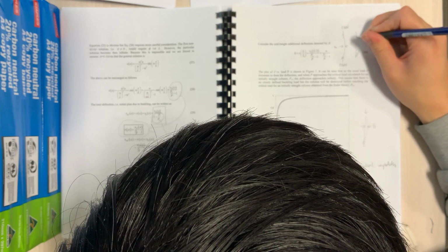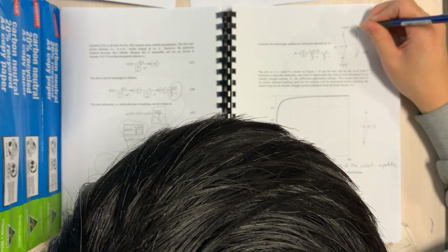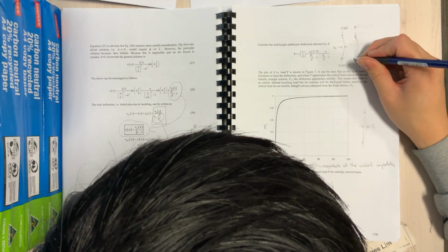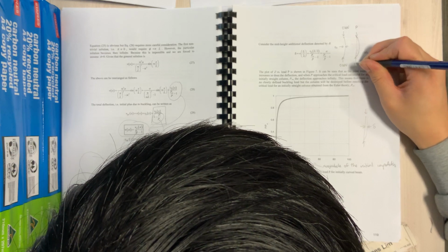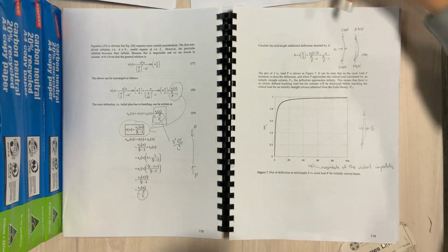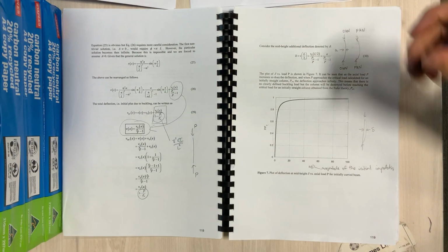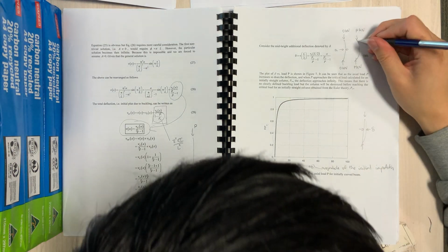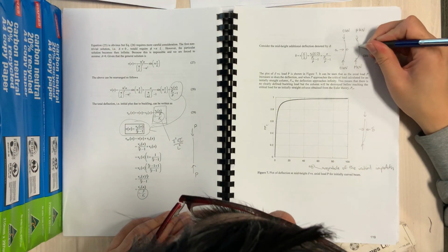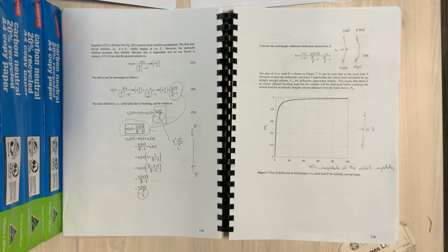And we're sticking a load on. So we're sticking an additional load on. That's P kilonewtons, and that would be P kilonewtons. So we're moving from the 0 kilonewton state. I'll get rid of this line there as well, just to show the exaggerated imperfection. As we talked about yesterday, these imperfections are not detectable to the naked eye. So you may need to use a laser scanner these days or something else in order to measure it.